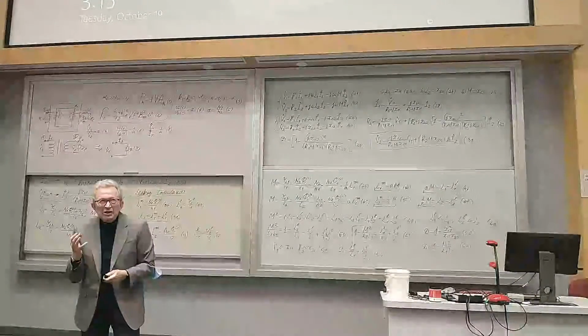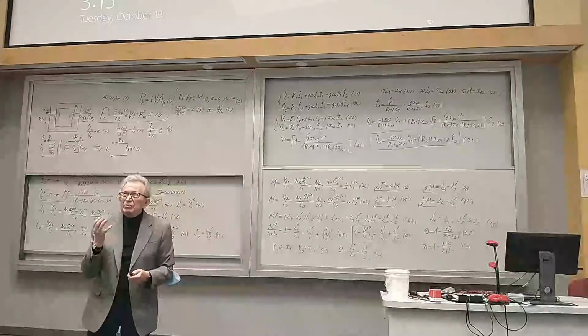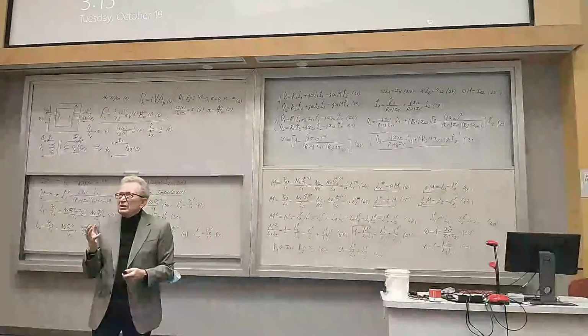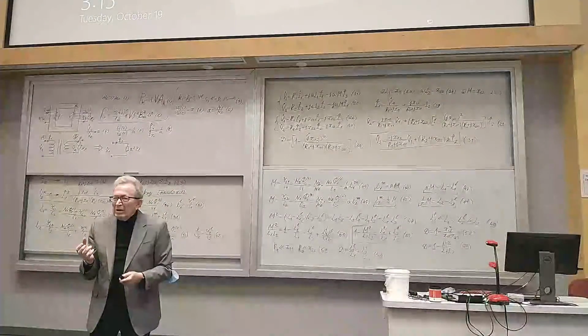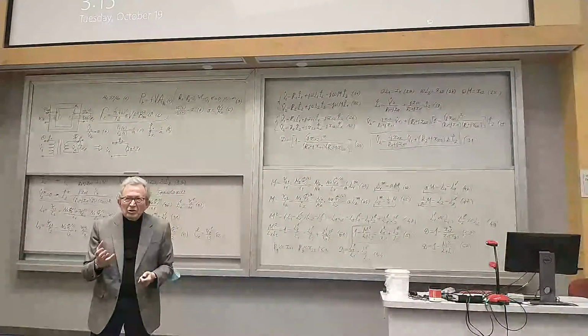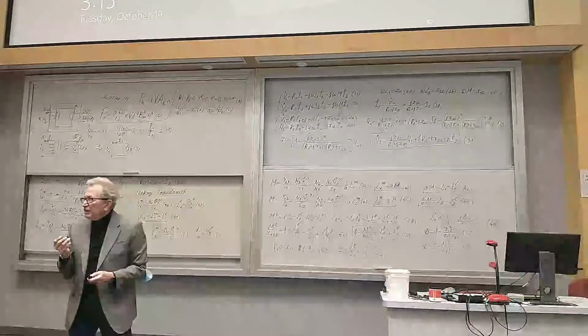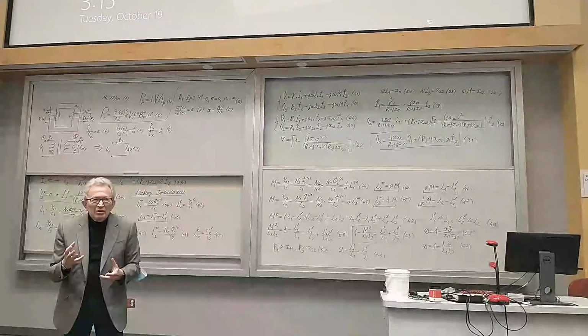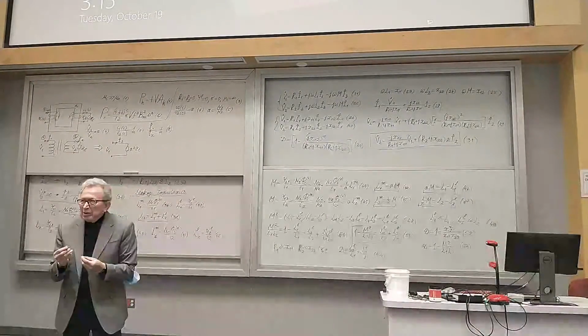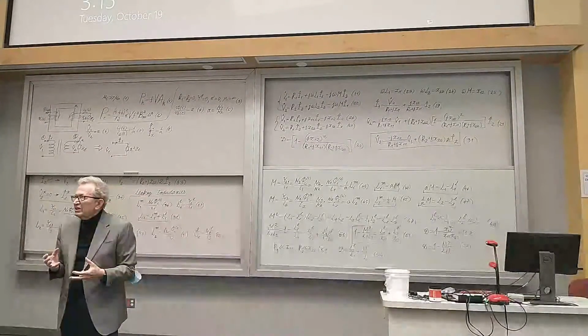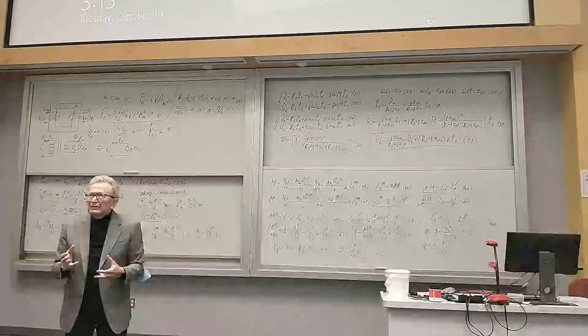Its ability to maintain more or less constant voltage in the face of continuous and predictably changing load, and its vulnerability to the short circuit situation. So it means that these leakage reactances are very important. We deal with a situation when small parameters are extremely important. They cannot be neglected.